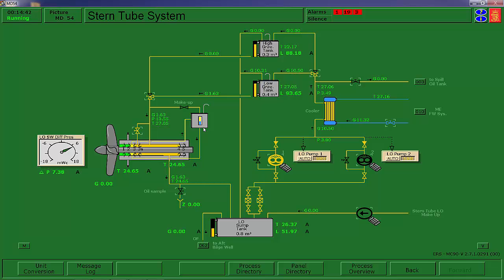You're going to see the top flukes of the propeller sticking out of the water when it's this unloaded. Now, when it's loaded, depending on the vessel, an ultra-large crude carrier can be as much as 20-meter draft change. That's 60 feet. So if that propeller is 60 feet lower when it's fully loaded, that means that the hydraulic water pressure outside the stern tube is going to dramatically change.